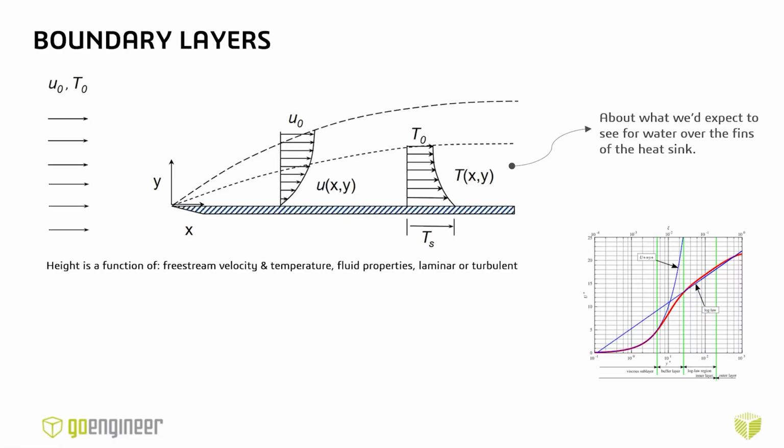They are actually very commonly used in other areas of CFD. I had briefly mentioned airfoils at the very beginning of the presentation. High aspect ratio elements are used when we're predicting lift and drag around an airfoil. We use them around the trailing edge of an airfoil. Some of that idea is built around the idea of a boundary layer.